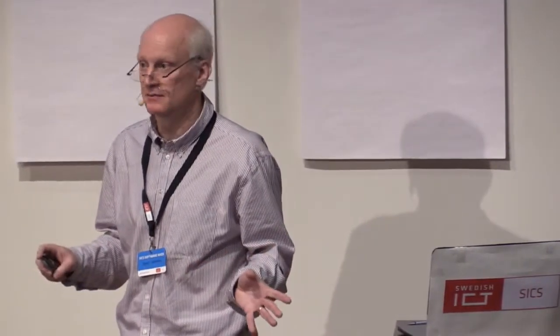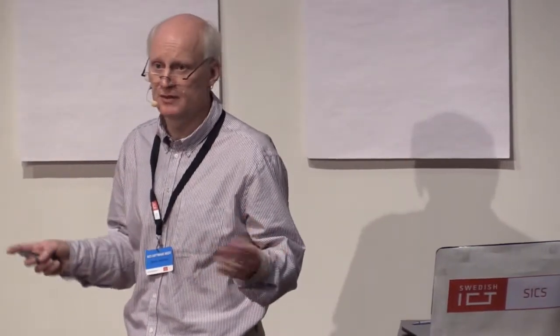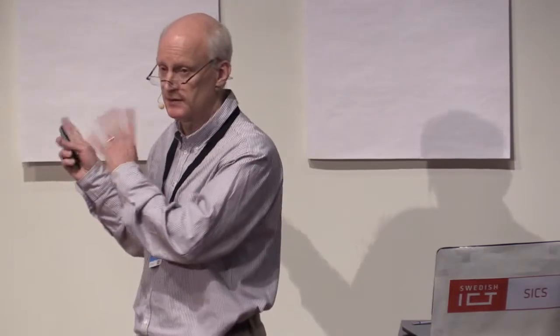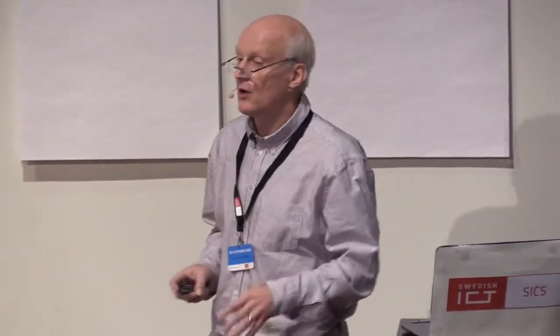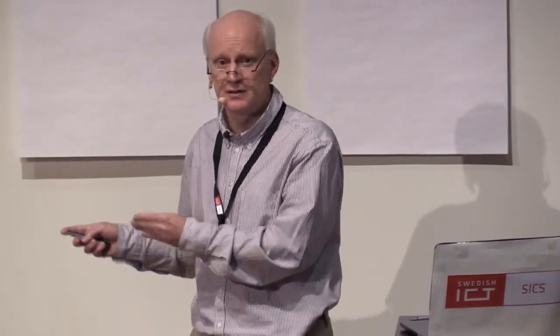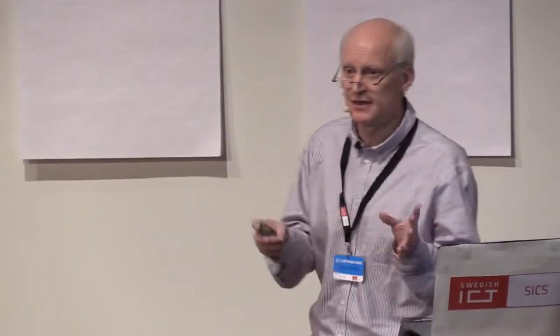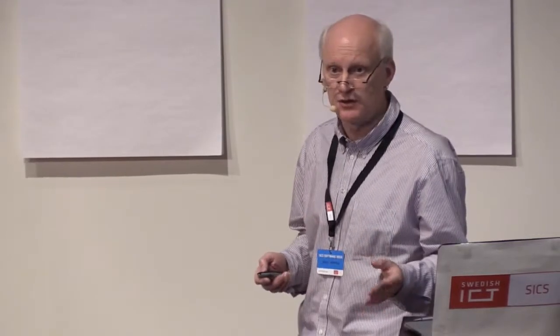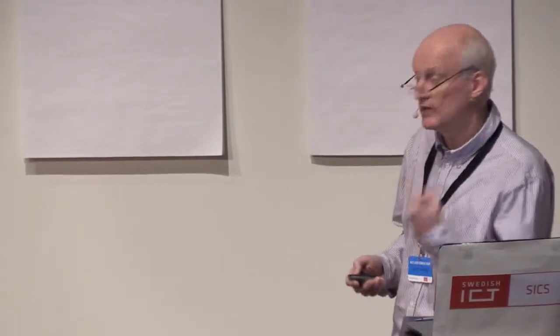Now you might argue, aha, you really don't need a deterministic simulator to do this. No, that's true. As long as the test passes, it's okay. You could have a non-deterministic simulator and just say, well, the system booted, I'm fine. However, if there is an error, you really want it to be deterministic so that you can do sort of a bisection and find out where it is going wrong when you rerun the boot.